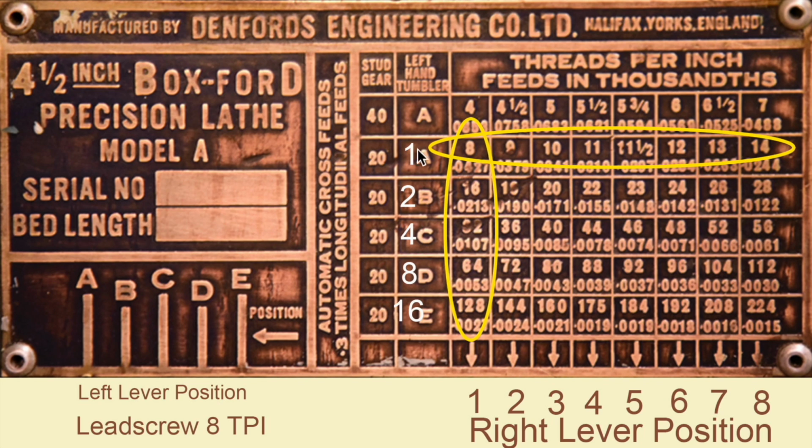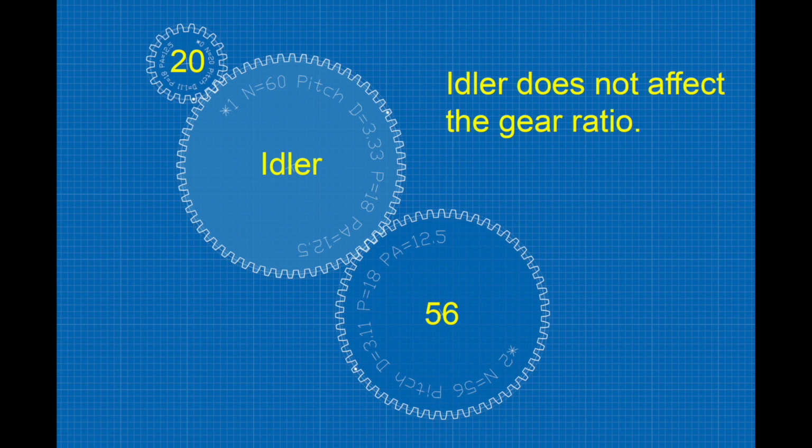I call this process of dividing by 8 normalization. All of this is done automatically by RideTheGearTrain, but this is how it works. Now that we've worked out the gear ratios of the gearbox, we need to find out what the correct gear train is to use with the gearbox. If you don't use the right gear train, of course, you're not going to get the right gear ratio.